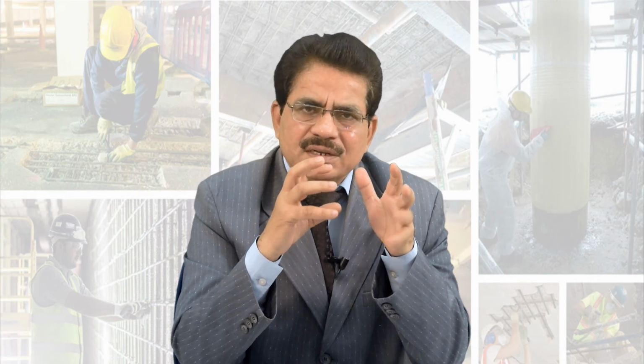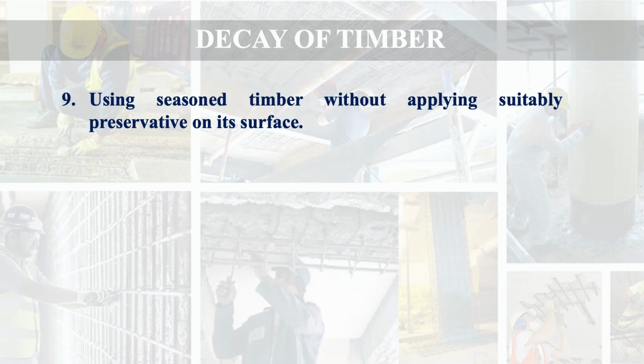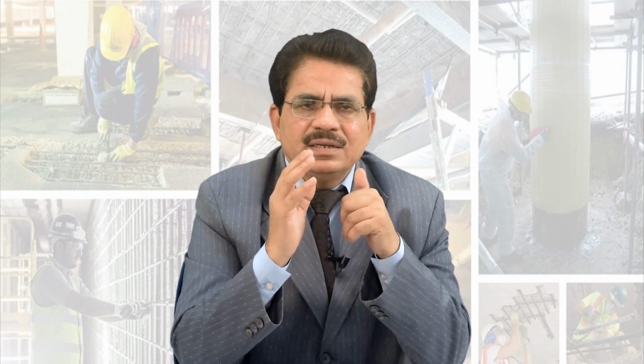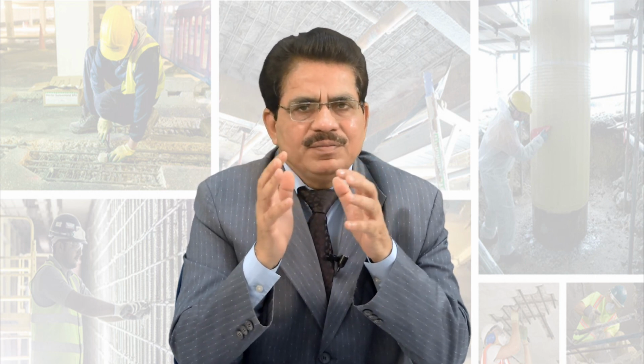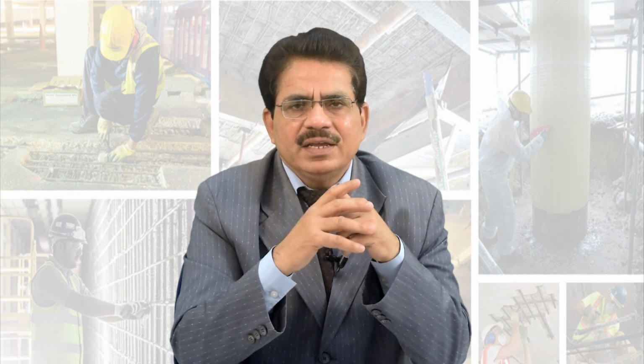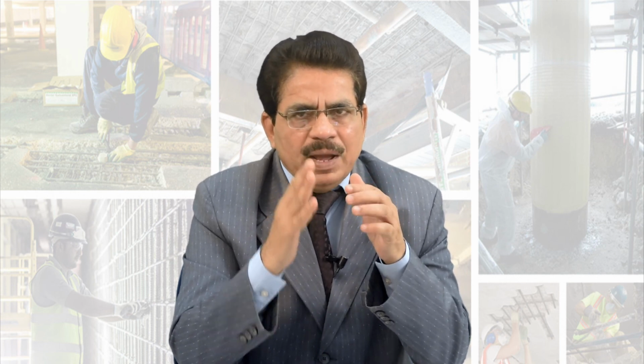Any wood which still contains the sap wood, if you are using it, then certainly it is going to decay early. Then using seasoned timber without applying suitable preservative on its surface. Here you look that only using the seasoned timber is not enough to ensure a long life of the timber. Even the seasoned timber may be attacked by insects and fungi. So to preserve it, to make it safe, we have to apply preservatives on the surface of the seasoned timber.